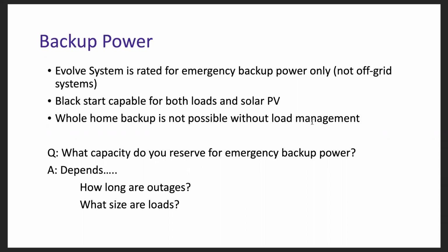And in my opinion, you're not backing up the whole home if you've got to add extra components in order to shed those loads. We won't get into too much of that here, but just be aware that loads are required to be relocated into a dedicated backup loads panel with PV for this system.